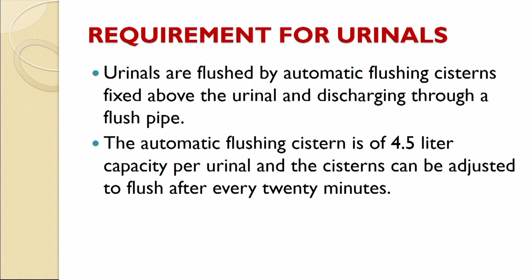Nowadays even lower capacity with a proper pressure flushing system is also present, and the cistern can be adjusted to flush after every 20 minutes. So that means you have to design the flushing system in such a way that there should be a proper flush after every 20 minutes.